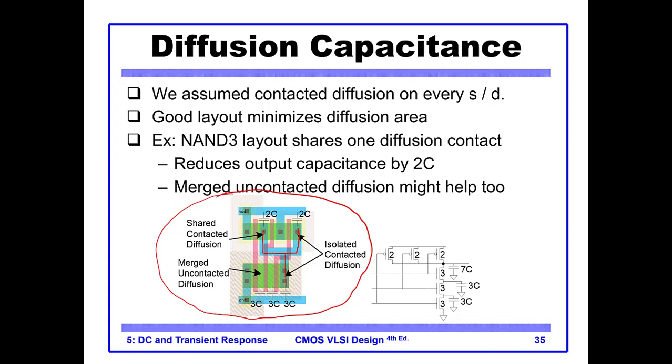Two PMOSes are on the shared line. Similarly, if we look onto the VDD, that's how it is connected. So you see that these two transistors share the same capacitance. Okay, so it is shared diffusion capacitance.